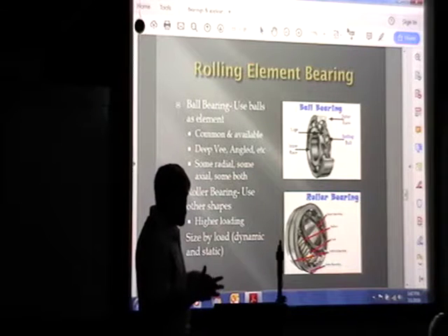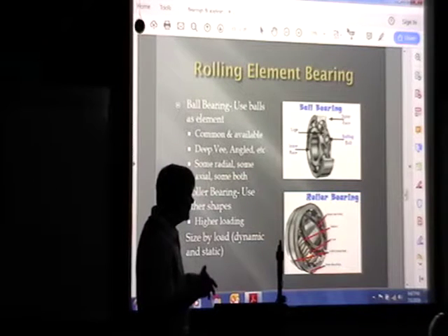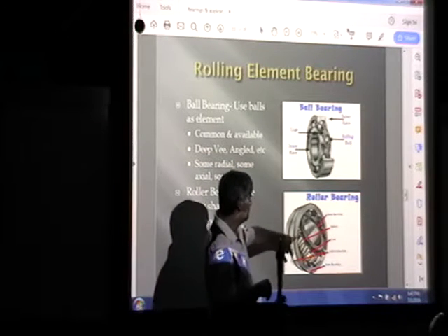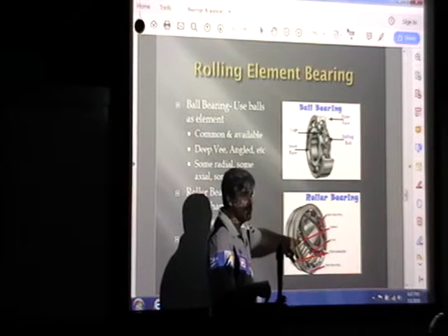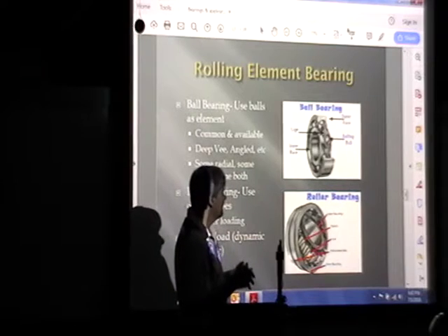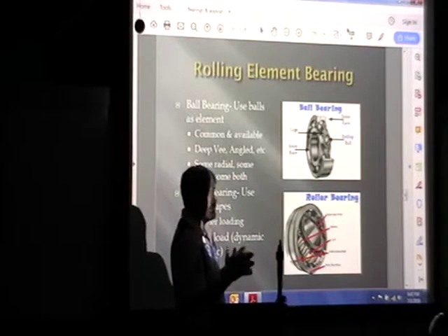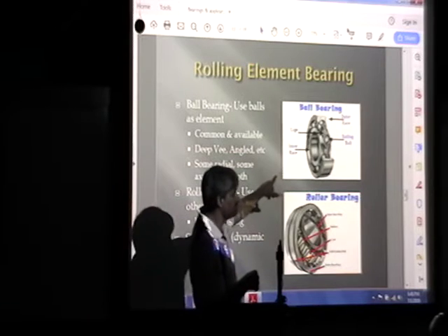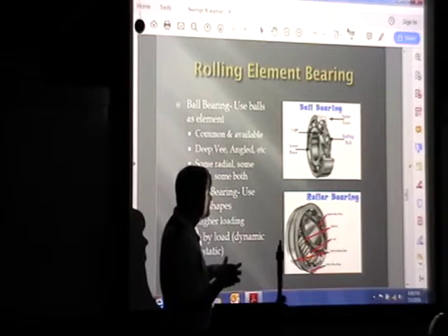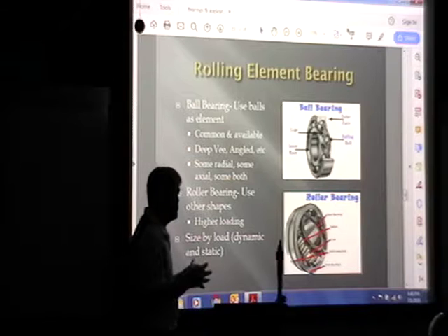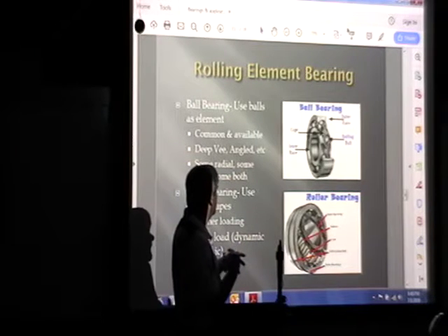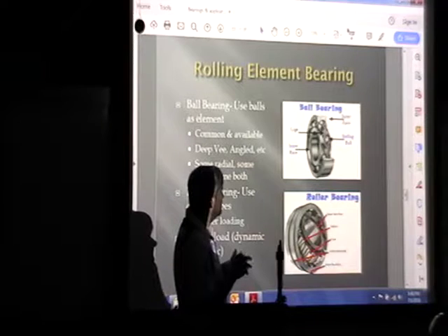It's that same kind of construction down in a roller bearing, and instead of the balls, what you end up with are cylinders, or sometimes needles. They're called roller elements. This type of bearing here can take a lot more load than this can here. Heavy industrial applications.